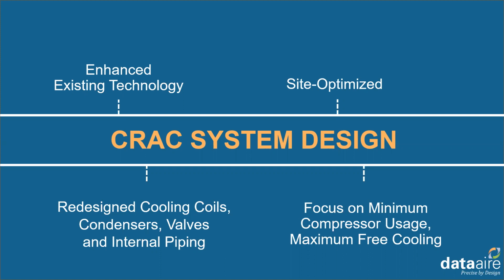Dual cooling units have 2 cooling coils. One's a refrigerant coil that uses the compressors to make cooling, and the other coil is the energy saver coil that uses water from the cooling tower for free cooling. We made a lot of other changes, though, to achieve Swanson Ring's goals. We replaced high pressure drop coils with low pressure drop coils, both on the air side and the water side. We replaced the valves in the unit with lower pressure drop valves. We changed the internal piping to take advantage of every gallon of water from the cooling tower.